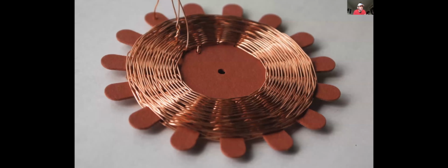Exactly. So there are two ways you can do that. You can do that with these magnetorquers, which are just a big spool of wire that interacts with the Earth's magnetic field, or you can do that with these reaction wheels, which are wheels that spin sort of like a bicycle wheel and then reorient you. And as we said, oftentimes this is a separate system, a separate computer that's dedicated to the task of orienting the satellite.